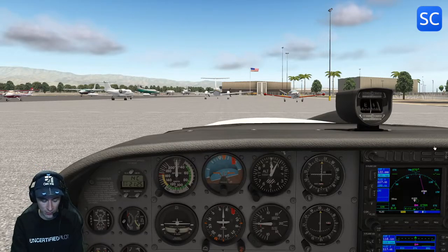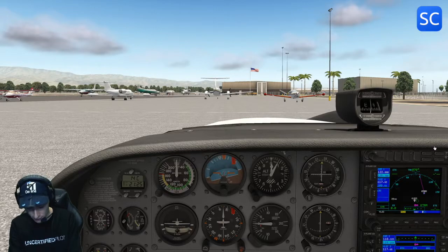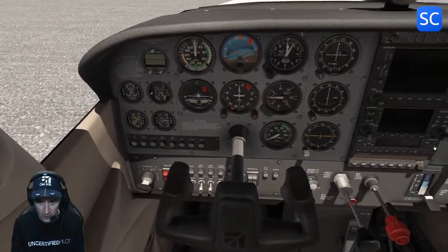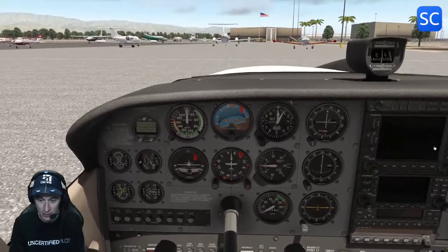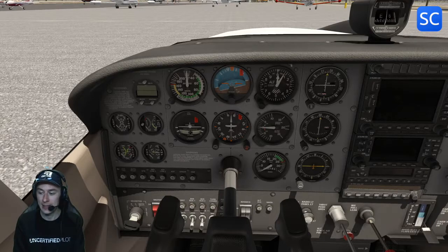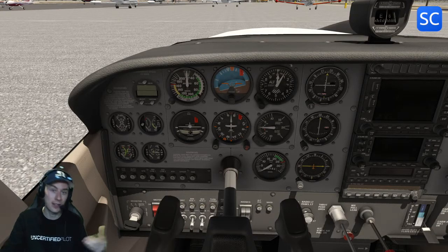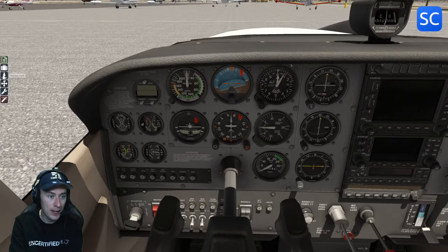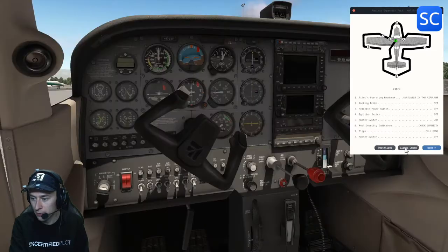Finish, turn all of those lights off because it drains the battery, obviously. Avionics should have been turned off already, and batteries off. And again, our battery is discharging, so if it's discharged enough, we cannot start our engine anymore. Important stuff. So, internal systems are working, but also we know that our lights and our pitot tube heat are working as well. Let's go outside. Walk around, and now the pre-flight.